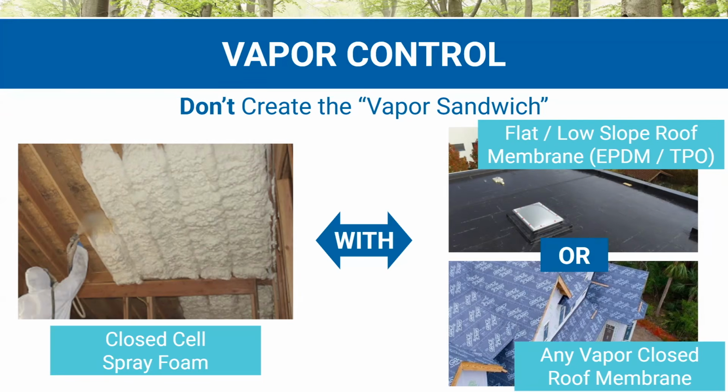The spray foam companies will say, well, you're vapor closed on both sides, so no moisture can enter. That is theoretically true, and that's what the modeling will show. But these materials start off wet. Wood is quite wet, so it would have to be bone dry. And the other thing is that wood moves based on its moisture content and expands and contracts.